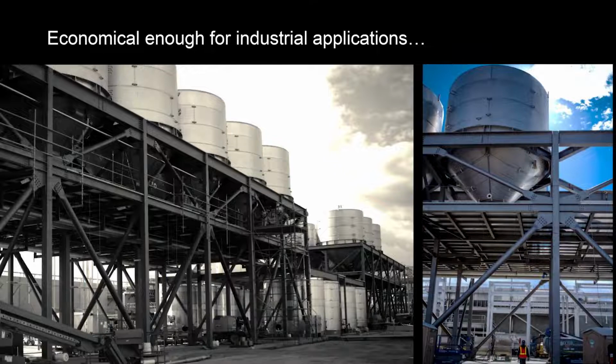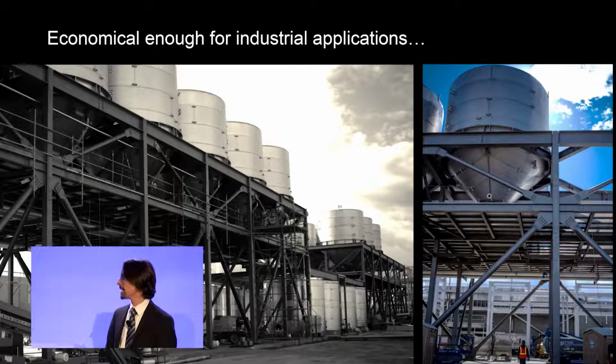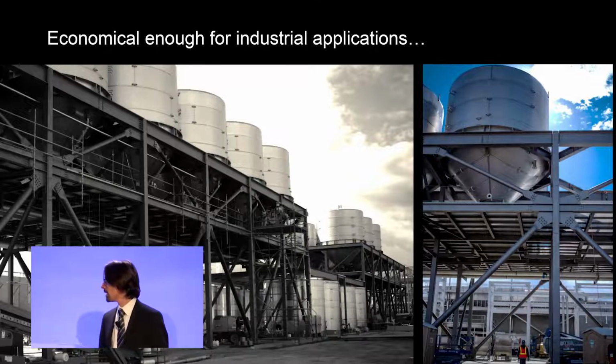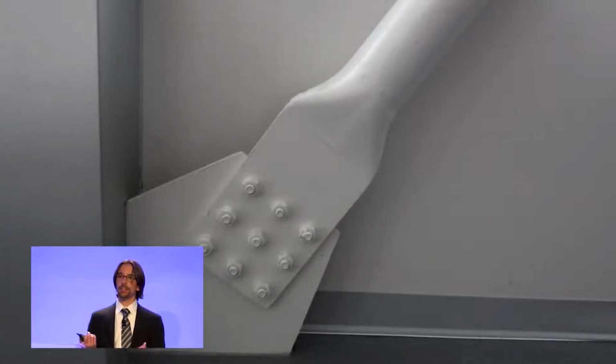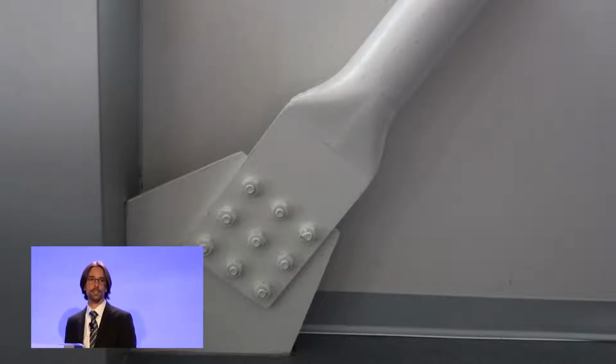So here you can see those connectors used at the ends of those braces that are supporting these very heavy tanks. This is in an industrial facility in California. But that same connector that was designed explicitly for functional purposes and seismic resistant connections often gets used in architecturally exposed steel as well.